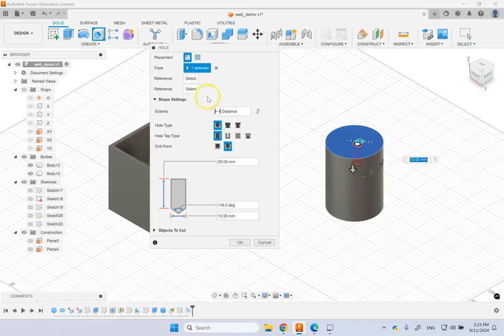So let's say I want to set the size of this hole and its depth. There are different types of holes: a simple drill hole, counterbore, countersunk, a clearance hole, and a tapered hole with an angle, flat, or angle with a drill point. In this case, let's say a simple one with a drill point at the end, not flat. And the depth I want, let's say, 30.